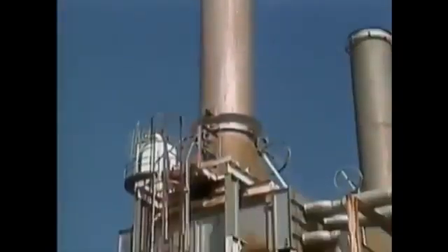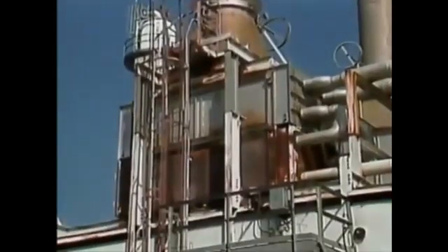If the flue gas temperature is too high, there could be a fire in the convection section, or the furnace may be operating above the normal firing rate. An excessive firebox temperature can overheat the tubes and refractory and damage tube supports.